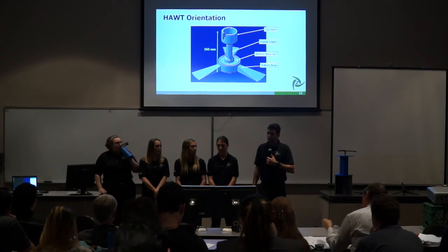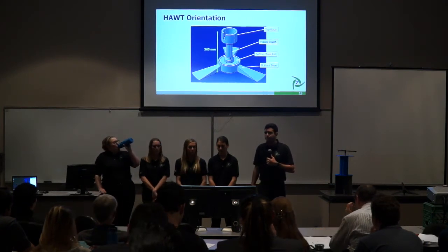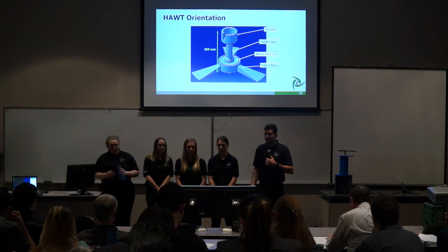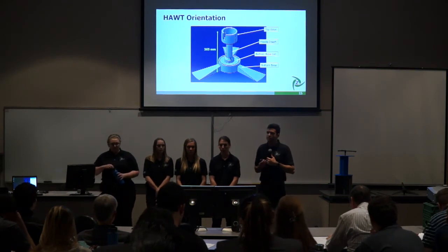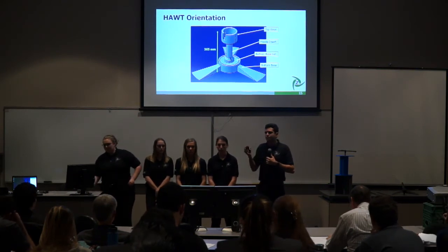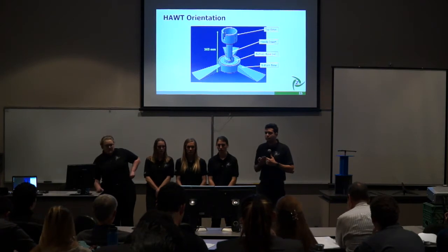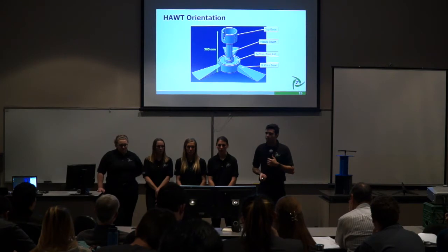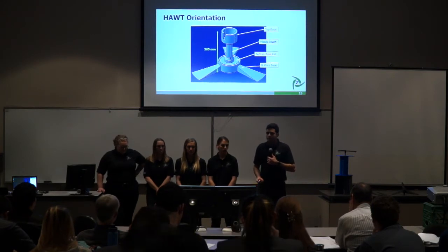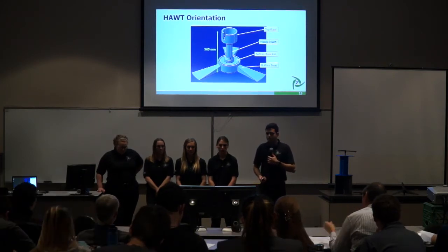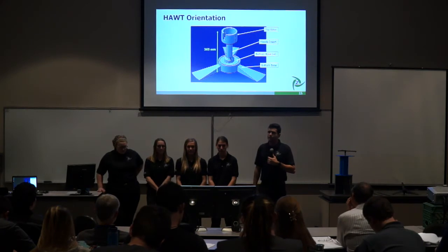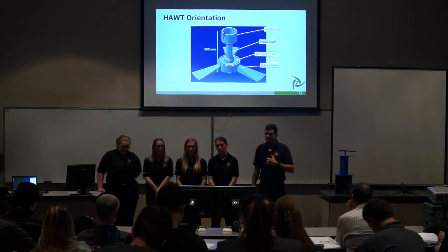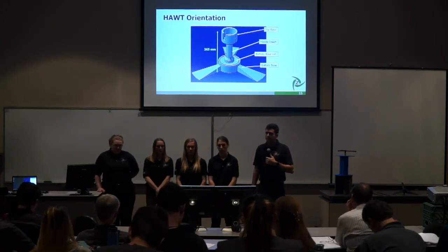These dimensions were more based off of the clearance of the blades. For our hot design, we did do calculations to find the minimum blade length we need to get the blade sweep area for our potential power output, as Tia was talking about with the potential wind energy. Therefore, the height of 365 millimeters is to allow clearance of the blade length from the bottom of the base. Okay.